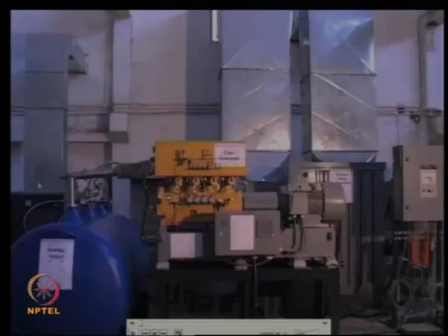The air which is getting compressed to obtain nitrogen also has an air compressor which needs to be cooled. So, cooling is done by air only, and the hot air which leaves this place is released outside at some higher point, so that people around will not be affected. So, this is the overall structure of the plant.